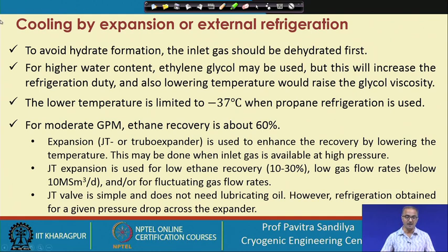Now, if there is too much water, then ethylene glycol may be used. As we learned, we may use ethylene glycol or other glycols, and they act as hydrate inhibitors. But if you are putting in these external glycols, first of all they also make our stream impure, and not only that, they will increase the refrigeration duty. That means the amount of refrigeration we need will also increase because of this addition of the glycols.